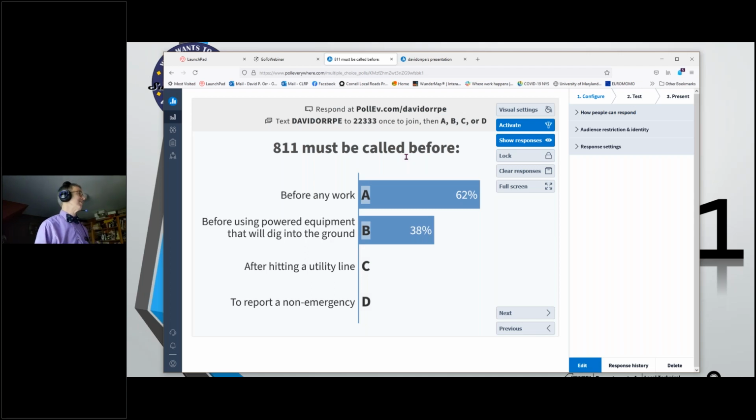I always look that up. Yeah, somebody got it. In Michigan, it's the same. It says anytime you do more than 12 inches. Okay. In New York State, it's anytime you use powered equipment. Anytime you use powered equipment, it doesn't matter if you're into the ground 1 inch.